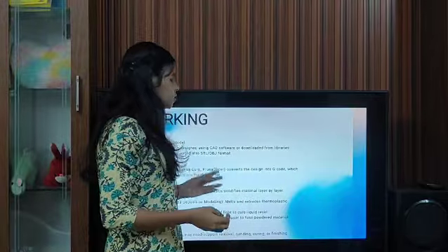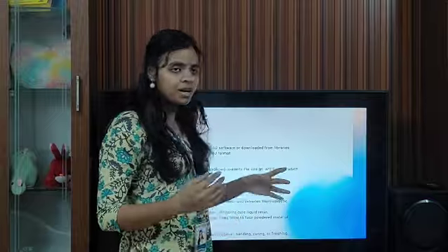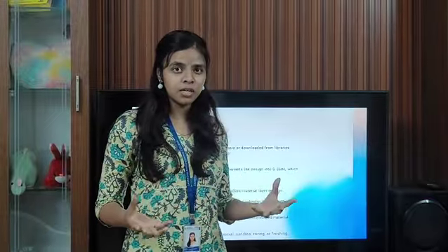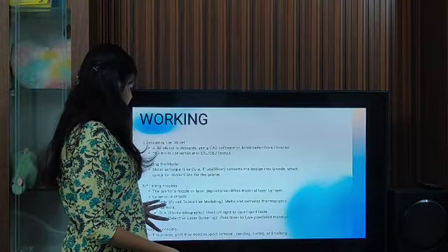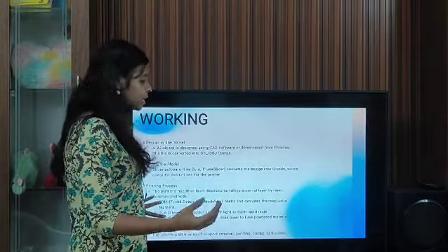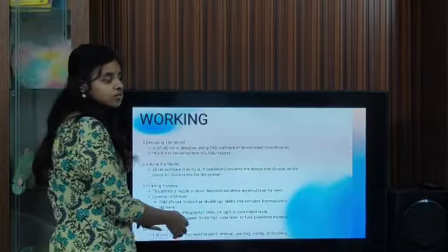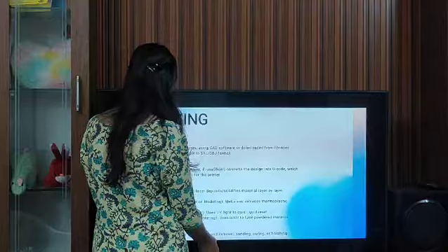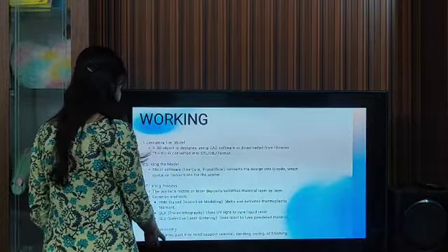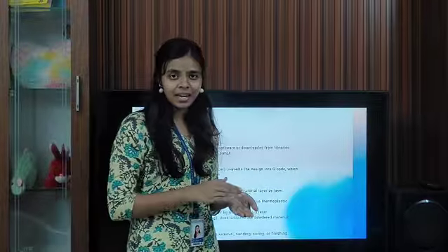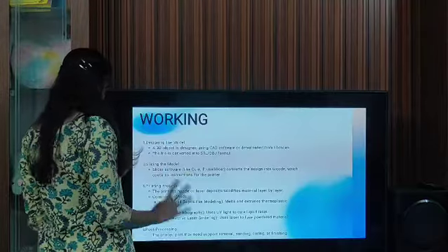Printing process. The printer nozzle or a laser deposits and solidifies material layer by layer until the final object is formed. Common methods: FDM, SLA, SLS. FDM is usually used for plastic printing. SLA uses UV light and is used in resin printing. SLS is used for fused powder material. Post processing. The printed parts may need sanding, finishing or cutting. This is known as post processing for the 3D printer.